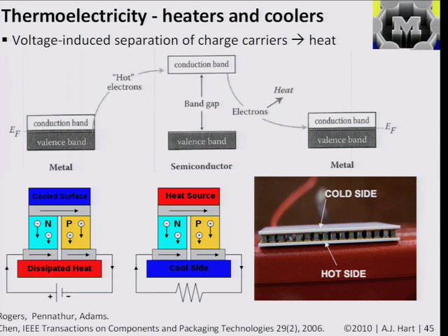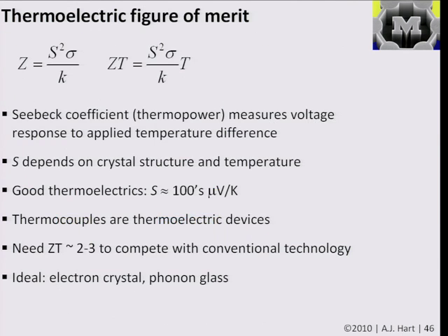So if you have heat and cold, it runs in reverse. And in a practical device, you might put together a whole bunch of these. So each of these little structures is one of these little legs. And each one generates a tiny amount of electricity, but if you put a whole bunch in parallel, then you can generate a sizable amount of electricity or a sizable amount of cooling. The problem is it's not really very efficient. So in niche applications, like in a satellite, or if you just want to cool down a chip locally without lots of messy water and so on, it will work.